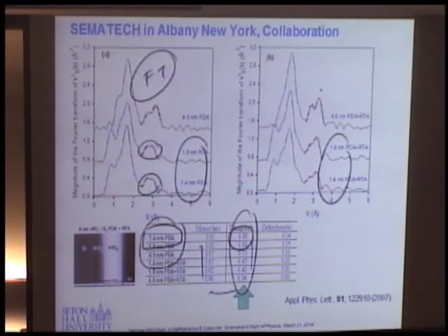This is the typical monoclinic phase. You got the double hump. If you have not a double hump, but also this one, that's showing a tetragonal. Of course, we're not doing it visually. We do a lot of XRD fits and get the calculated structures input at the fits output, and then we decide that's the case. And so they were very happy, okay?